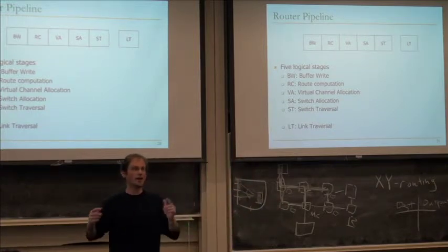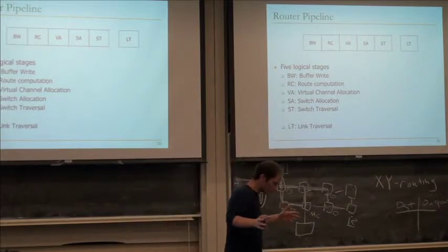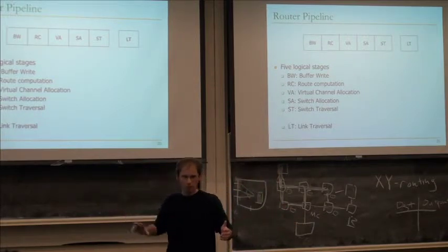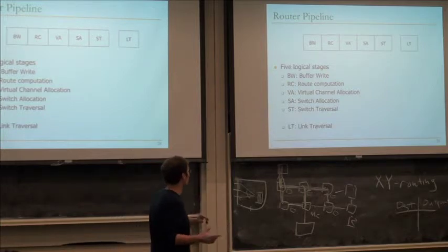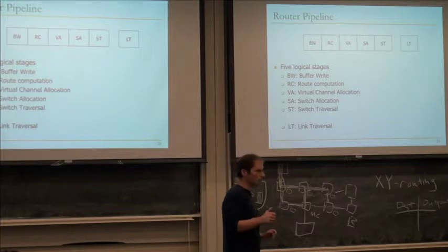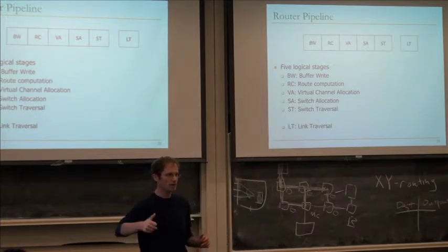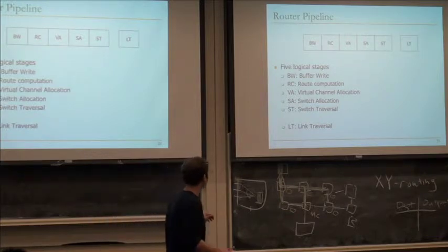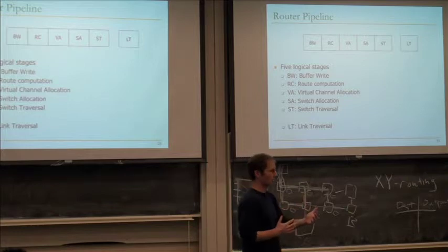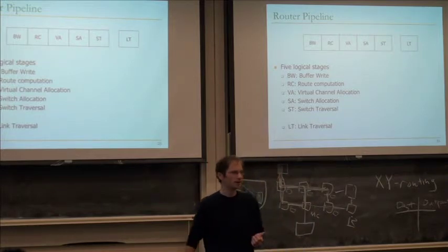Sorry, actually allocating a virtual channel, not space in a virtual channel. Once you have that space downstream, you know that the packet can basically move on because you know that it has a place to go. And then when it moves on, you'll tag it with a virtual channel identifier. So in the input buffer in the next router, it just goes straight into that virtual channel. So you can think of this as pipelining virtual channel allocation by one hop, where you actually allocate ahead.